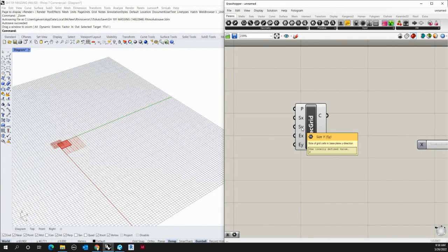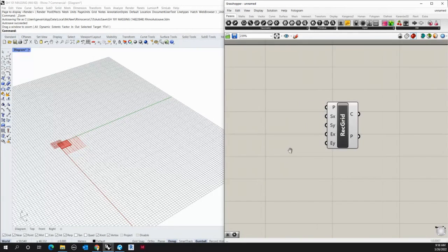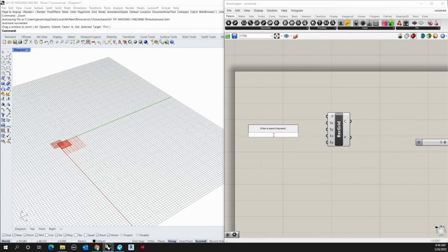Same thing in the Y direction. So a dimension for the grid in this direction. And then an extent X and Y. So this is going to be the amount of points I'm going to create from the grid in both directions. So let's get started. How big do we do it? Let's do a 20 by 20 grid. So we have 400 points total. So that's going to be my extent.